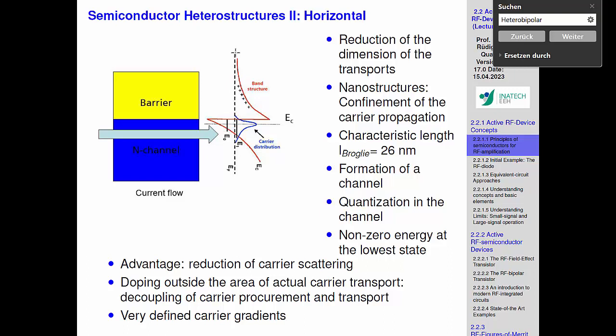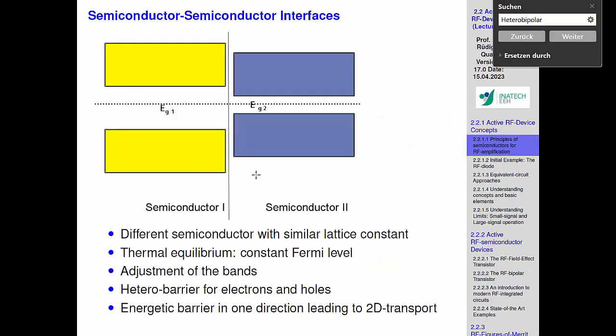So what will be needed is that they adjust somehow, because these conduction bands, because it's then one crystal, they have to meet. And if I do this right, I will get a situation where this is the larger band gap material going up. There must be some difference to accommodate the overall difference. This is material dependent, but if you make the right selection, there will be some offset here, and then you're going again to meet this band gap.